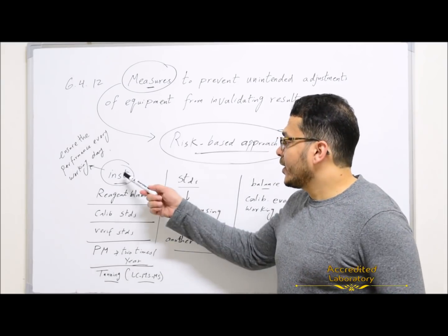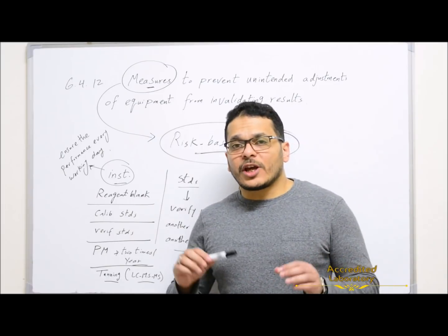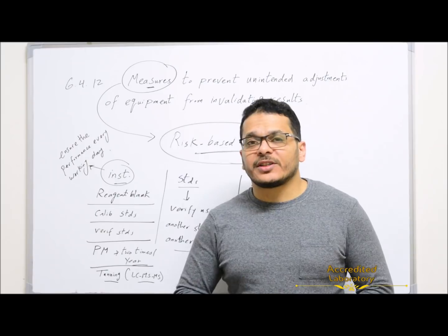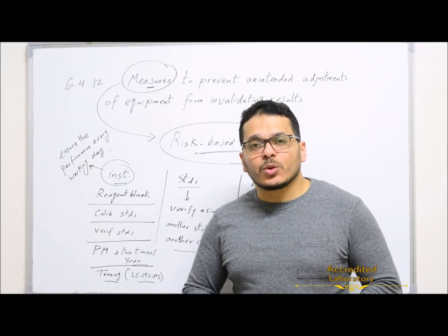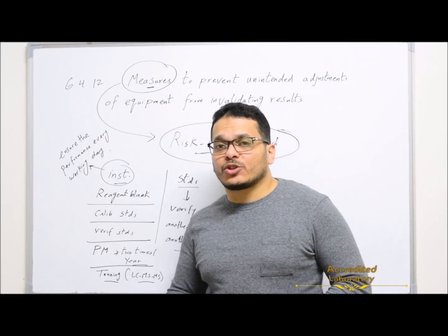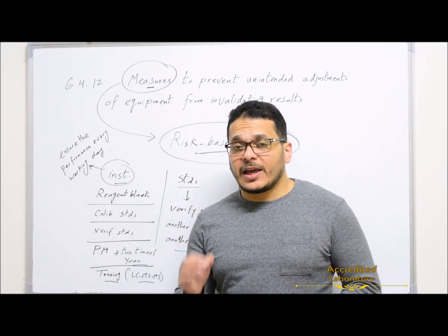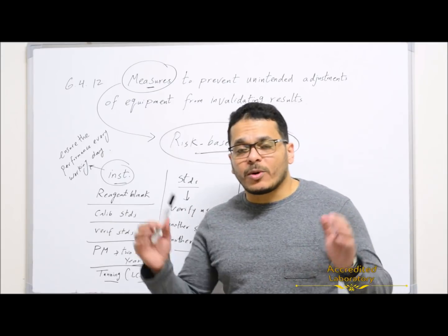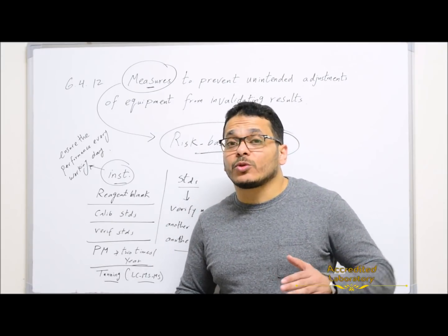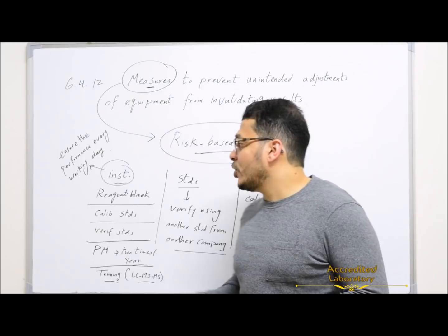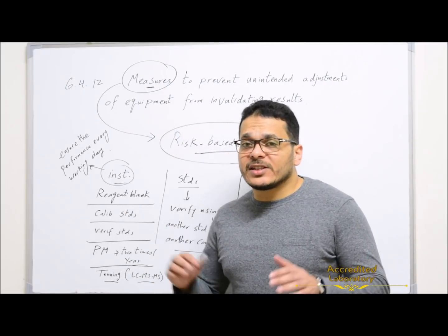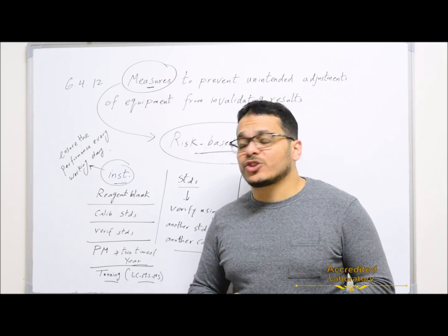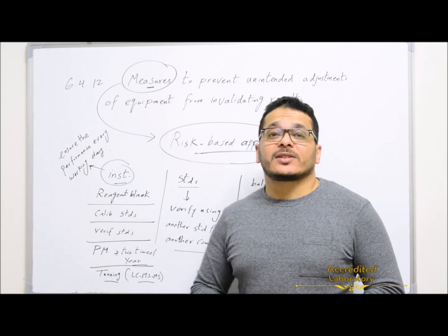As an example, the instrument. You shall ensure the performance of your instrument every working day. Before running the sequence, you shall ensure that your instrument is stable and performing well. You will run the instrument with mobile phase for some time until it is stabilized, and then you will run the reagent blank. If there is any contamination, you will know from that reagent blank, and that contamination will be removed from other samples.